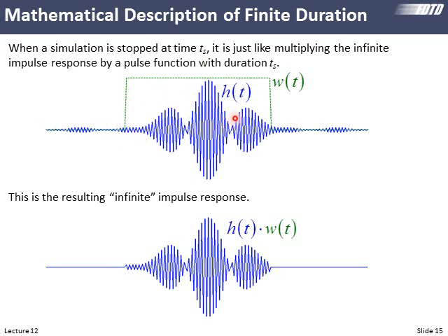It'll do whatever it does in the simulation, and it probably hasn't ended yet, but we will end our simulation, so we're not counting any of the stuff in our Fourier transforms or anything like that. So essentially, in terms of the spectral responses that we're calculating, we are setting everything outside of this to 0. So it's just like we took our infinite impulse response and multiplied it by this square window that encloses the duration of our simulation. So this product now looks like this.